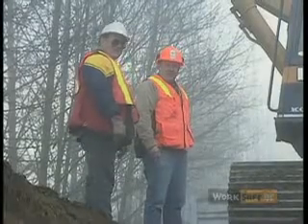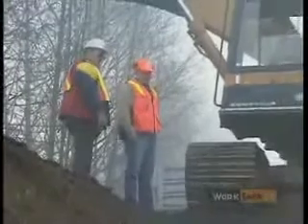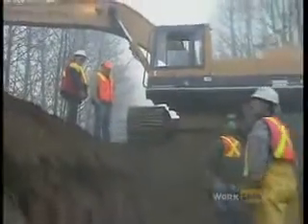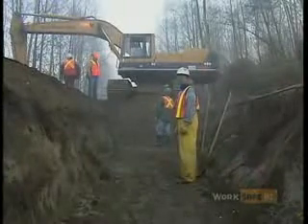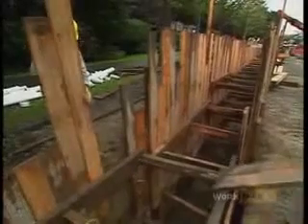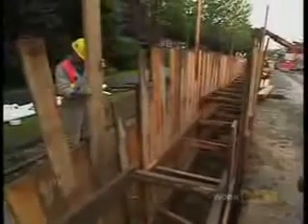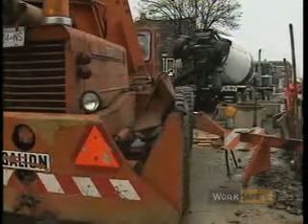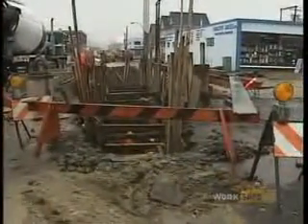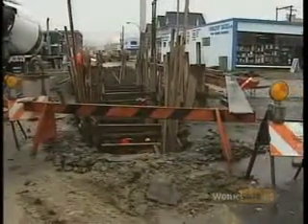Workers shall not enter any excavation over 4 feet in depth unless the sides of the excavation are sloped to a safe angle, the sides have been supported by the use of sheet piling or shoring and bracing, meeting the minimum standards contained in the regulations, or the workers are protected by other effective means, such as restricting worker access to the hazardous area.